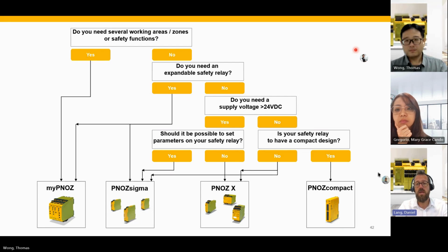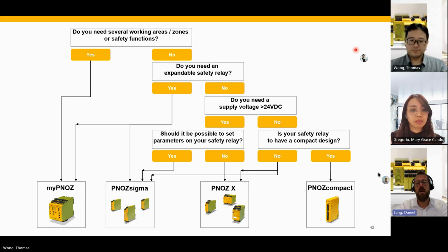So if you have an application where, let's say, in one hour or one day, there is a high amount of opening and closing of contacts, then the best fit would be a semiconductor output. And if not, and everything is fine, and perhaps you also want a little bit less wiring effort, then you stick to the relay contacts. Okay, I hope we answered your question, Pak Ur. If not, you can always contact us again.